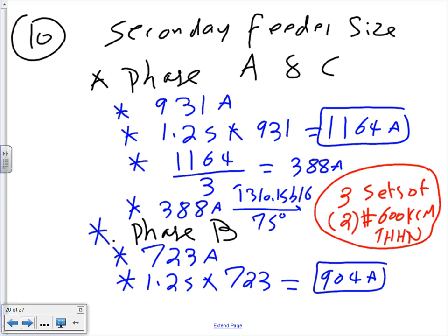Could I run these two sets? I can. But if you do it this way, then you have to put them in different conduits. Typically, we put the 3 phases in the same conduit, guys. You have to if it's metallic conduits. Otherwise, you have induction heat. So since we're going to be putting the 3 phases in the same conduit, you're almost forced to parallel 3.